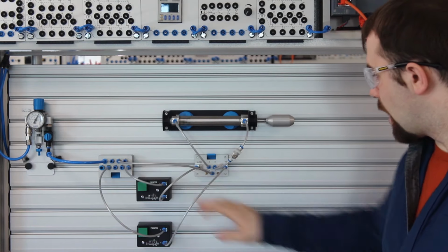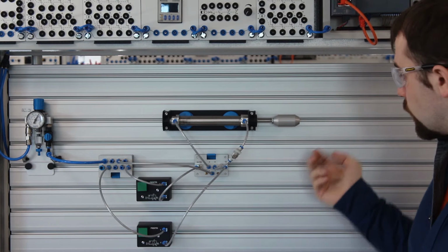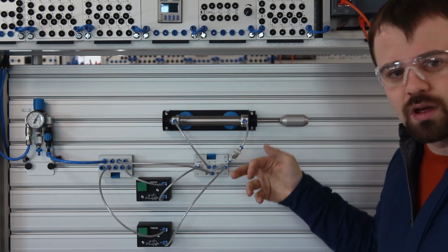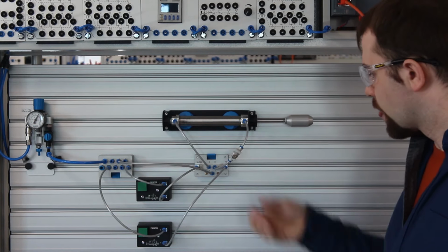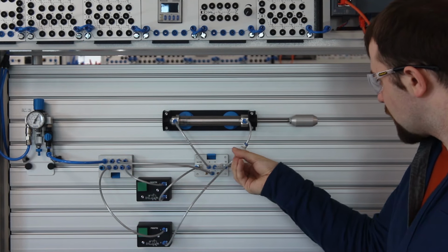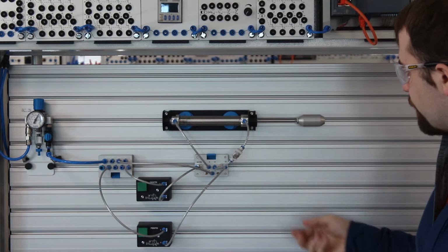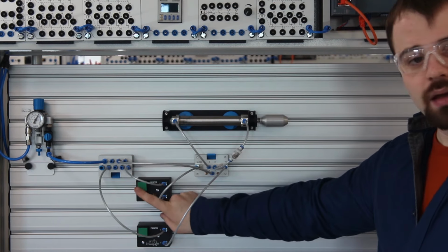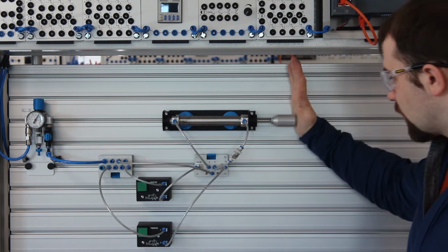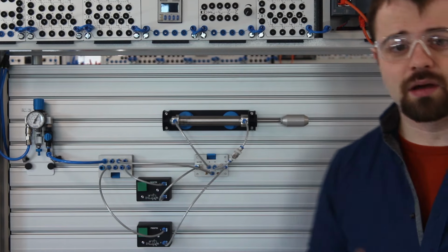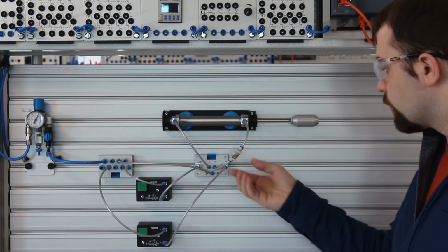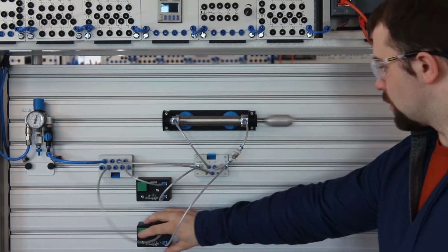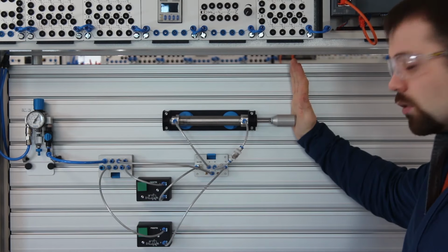So, air on, cylinder starts moving forward, and I can kind of stop it in its place, but I can't push it backwards. That's because it's got full force behind it. Maybe I'll speed it up just a little bit. There we go. So, back and forward. And again, you can see I'm not able to spring it in the same way that I was able to spring it before. We have full force now behind the cylinder because we are restricting the output instead. Back and forward with force.